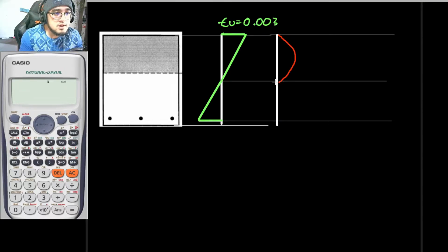And once again, since your concrete does not have any capability to withstand tensile stress, that is according to the USD, that is our assumption, we would not be having this particular stress right here. So we would just be removing this. But since we have our rebars at this part, the rebars will now be the one that will resist tensile stresses. So this is now it. So let's say that this is for your tension, and this is to be a distributed load. This should be a pressure.